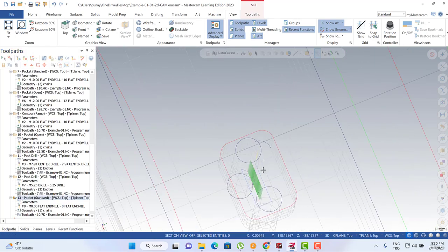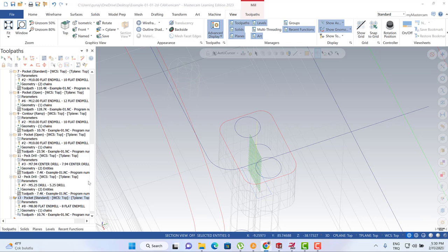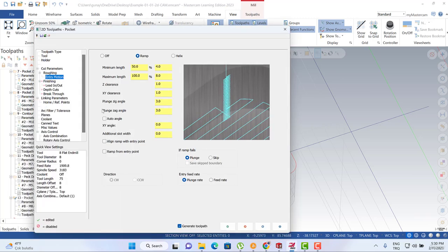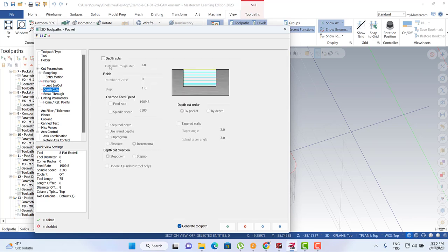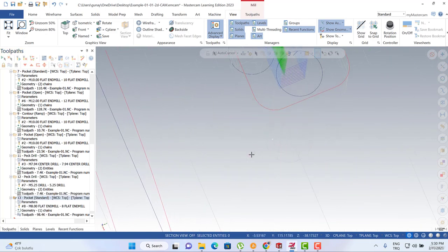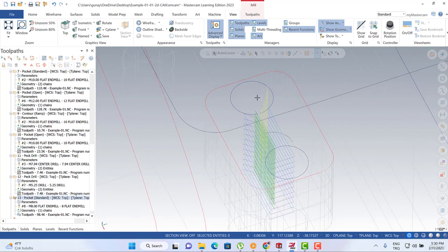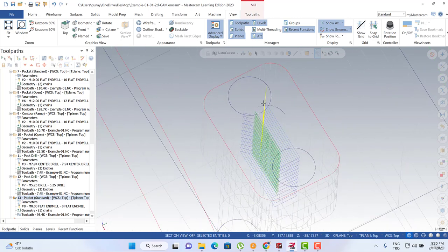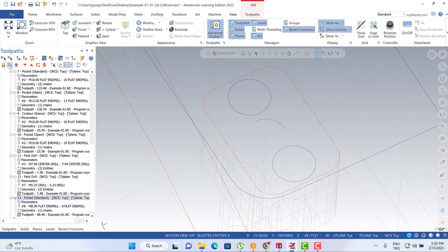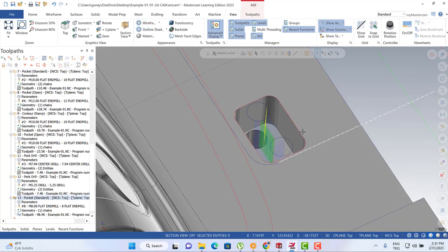And then we're going to see the toolpath here. Of course, we also need to activate depths here. Depths can be 1mm. Okay, that toolpath can be seen here. Everything seems fine. So it's a final position. Remember that this part is for roughing.